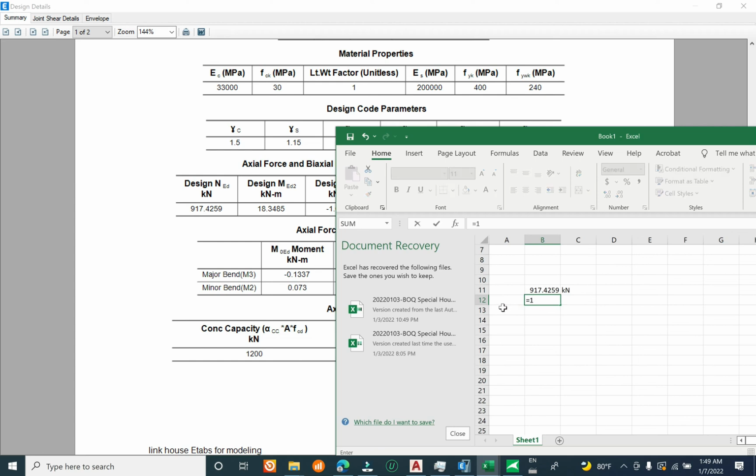For the BS, the British standard, for the United Kingdom, we use only 0.85, but in the case we use the default national annex, it applies 1 and multiplies with our section 200, multiplied with 300, and multiplied with our concrete strength of 30, and divided by the safety factor of 1.5 for the concrete.